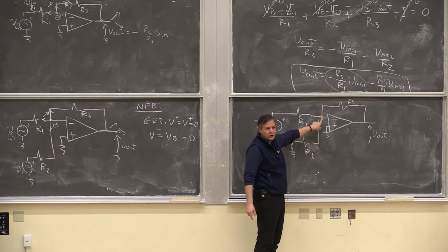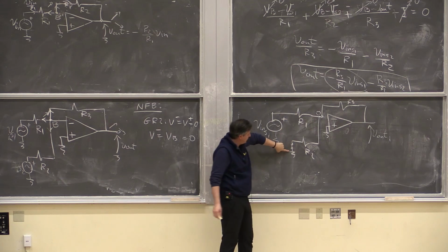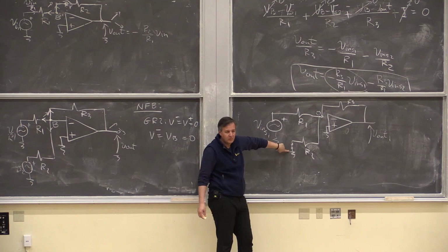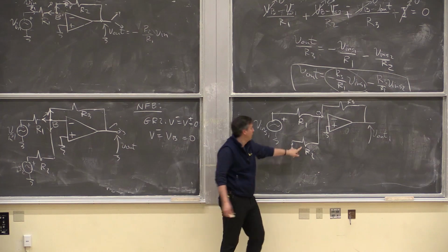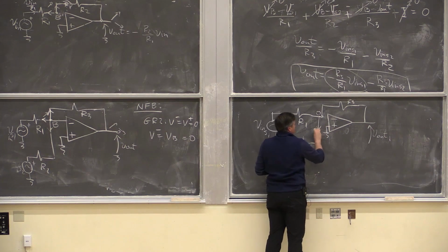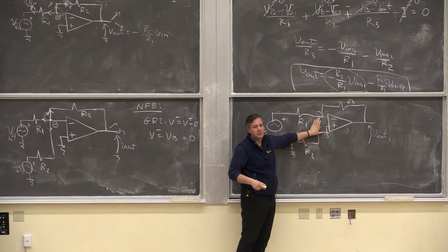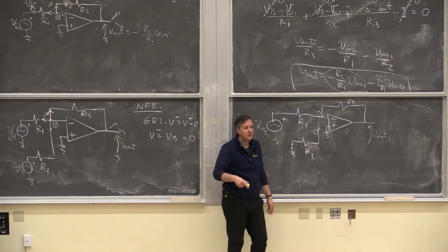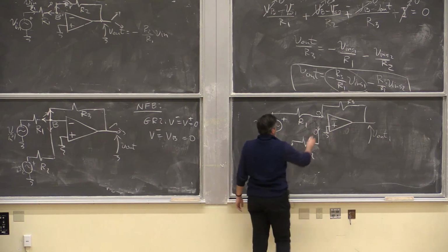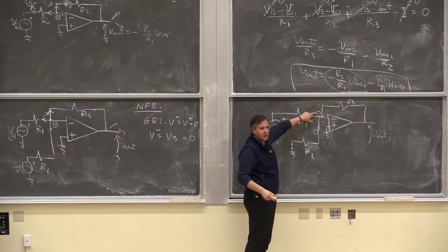We know what the voltage is here at node B, right? So 0. So there's 0 here, there's 0 on this side. Ground is on this side. What's the current through R2? 0, right? So the current is 0, I can just ignore the whole branch. It's like it doesn't exist. Yes? Actually, are we sure the current there is 0? It looks like there could be a voltage. Well, the potential on this side is 0.